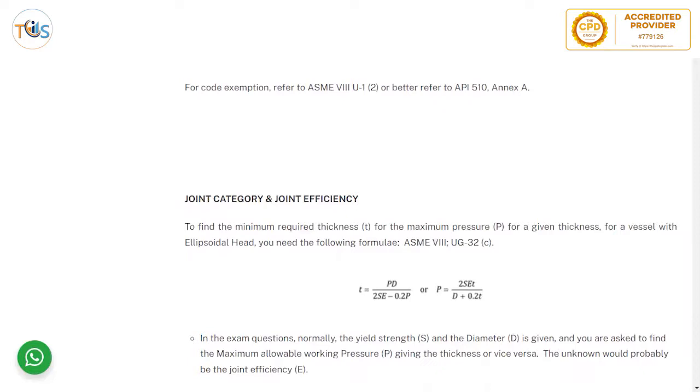So U1 is the form for the manufacturer, and U2 is the form for the part manufacturer, who is subcontracted by the manufacturer to make part of it. It may or may not need a U2 form, if the manufacturer fabricates everything himself.